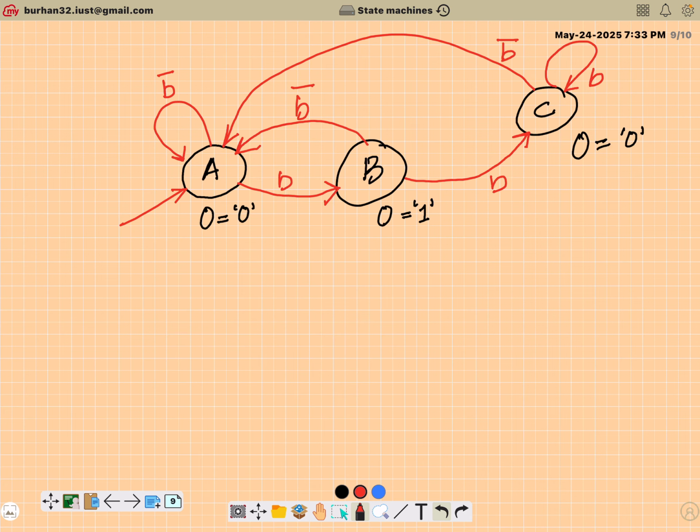Like I said, the foremost challenge here is to capture the FSM, and your FSM description should be complete. In the sense, for every state that exists in your FSM, you should be able to define the transitions. So this is the finite state machine. The rest we can easily code now that it is defined.